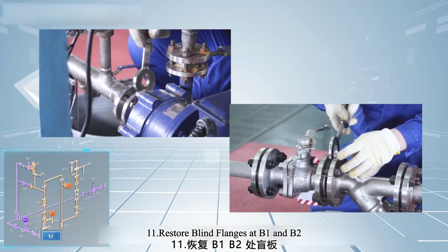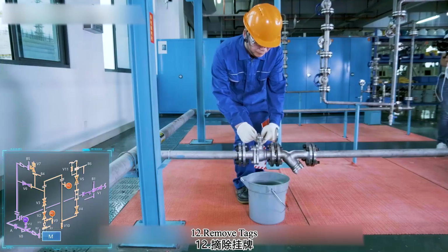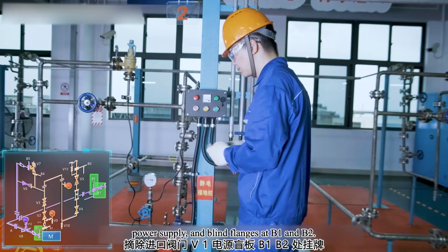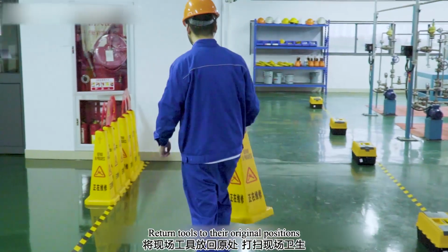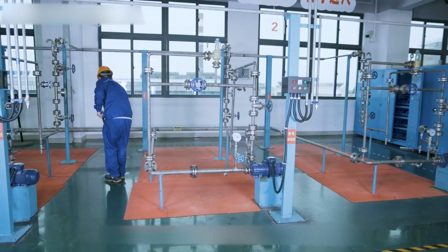Eleventh, restore blind flanges at B1 and B2. Twelfth, remove tags. Remove tags from inlet valve V1, power supply, and blind flanges at B1 and B2. Thirteenth, clean up the site. Return tools to their original positions and clean the work site.